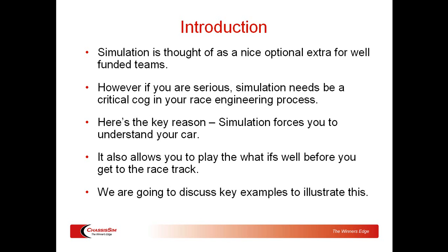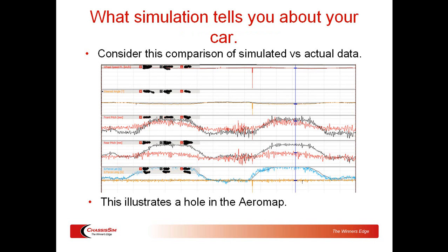So let's get started. The thing that simulation tells you about your car is that even before you've done any setup sensitivity analysis, you can glean so much from the correlation. Let's have a look at this plot of simulated versus actual data. Actual data is colored, simulated data is black. Let me walk you through the traces. We've got speed, steered angle, front pitch, which is the average of the front dampers, rear pitch, which is the average of the rear dampers, and we've got lateral G and longitudinal G.